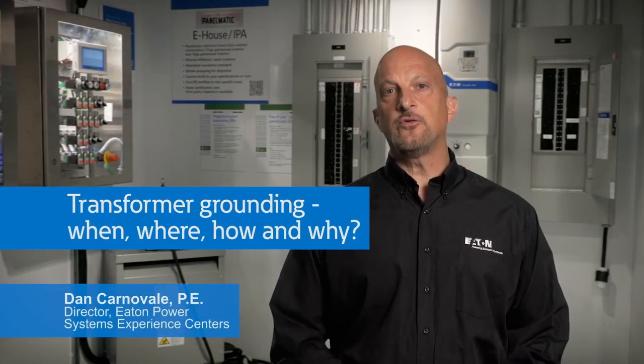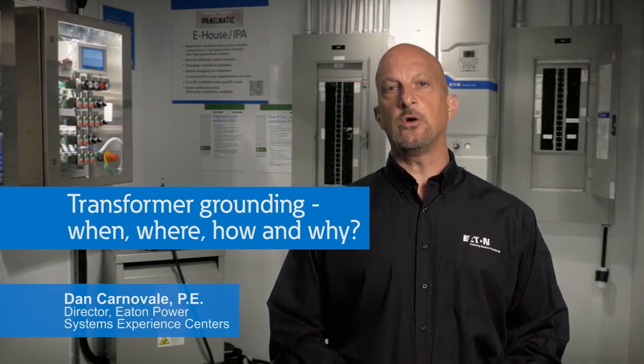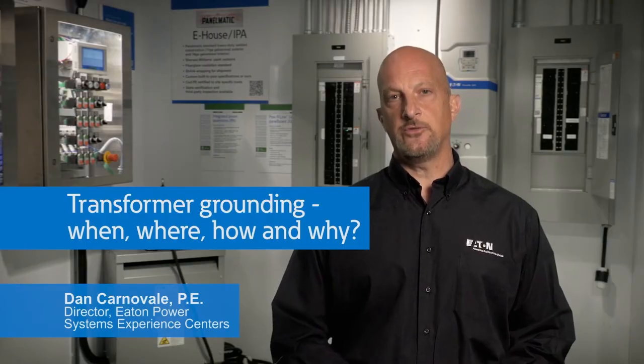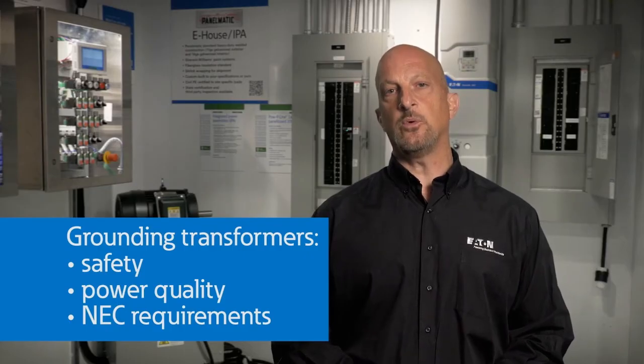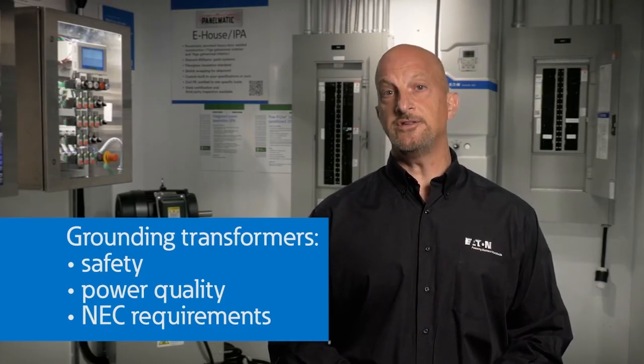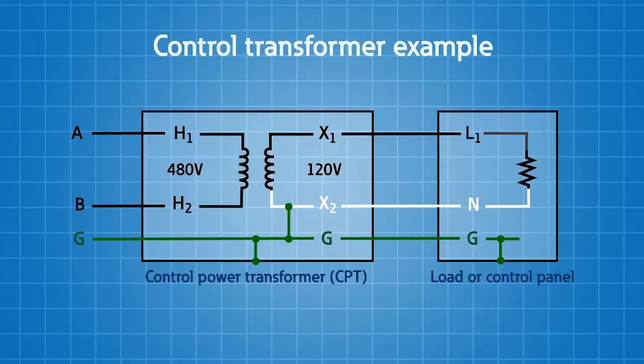With respect to grounding, transformers are often an area of concern and discussion regarding when, where, how, and why to ground the transformer. This is a simple single-phase example of a transformer, like a 480 to 120 volt control power transformer. Considering the secondary windings, one of the two legs, typically X2, would be connected to ground. This would allow you to establish a known reference on the secondary of the transformer when this is required for safety, power quality, or by NEC requirements. X2 is also considered the neutral conductor for typical low voltage applications and would only be grounded at the transformer and at no other point downstream on the circuit fed from the transformer.